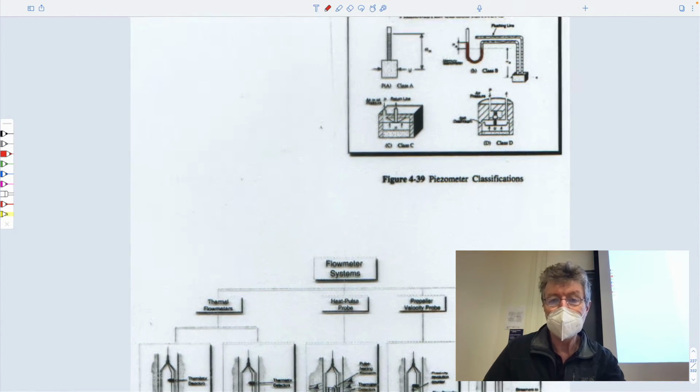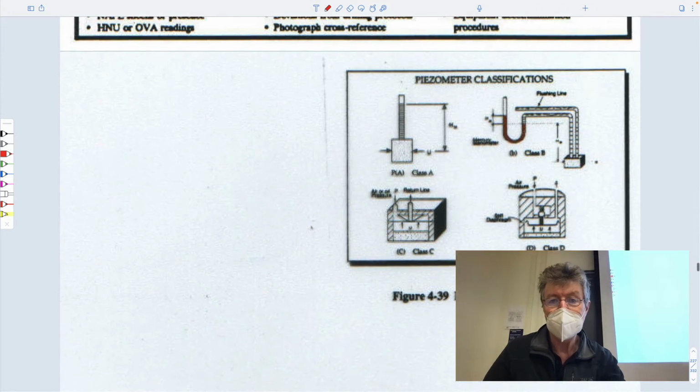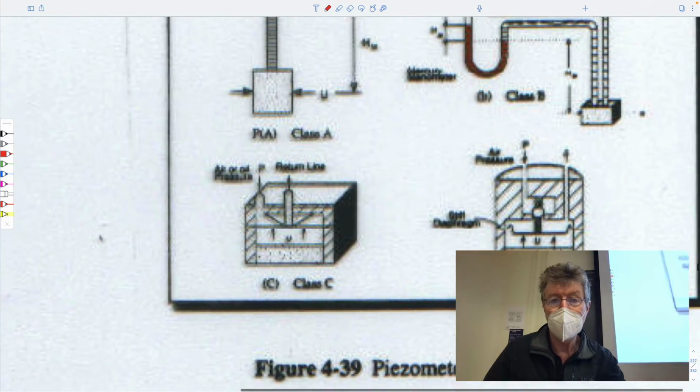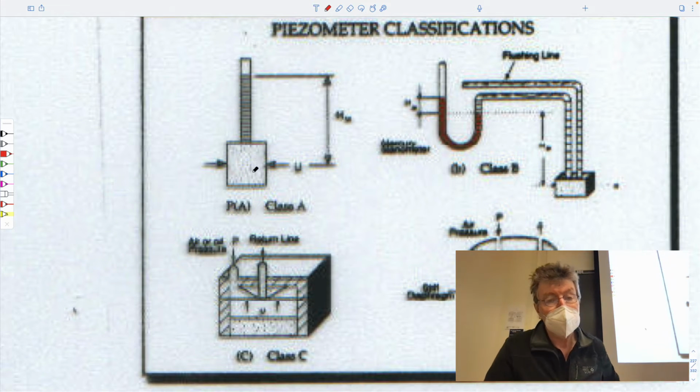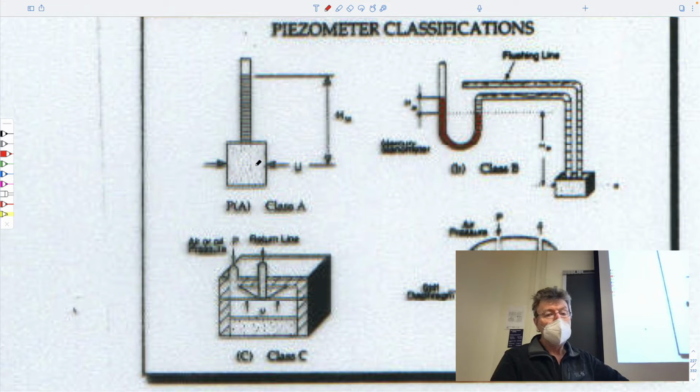Other things that you might do, as we've talked about, is at the bottom of your borehole, measure pressures or actually take water samples. The standpipe piezometer we just looked at in this borehole is exactly this. It's a zone of permeable sand that you've introduced in the bottom of the hole, and you have a piece of plumbing that contacts it that allows you to measure the elevation of the water within the borehole. So if you know what this is, you certainly know what the pressure is here.